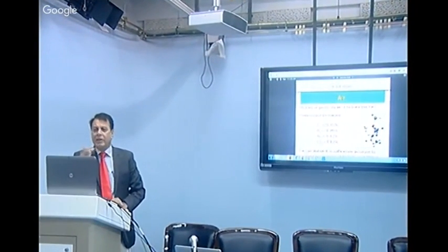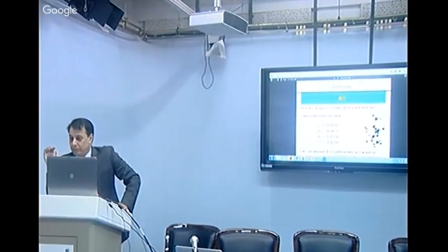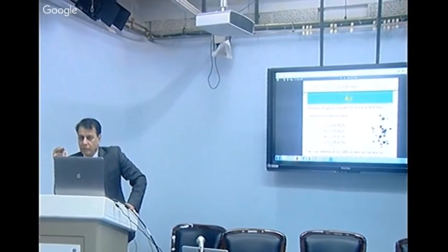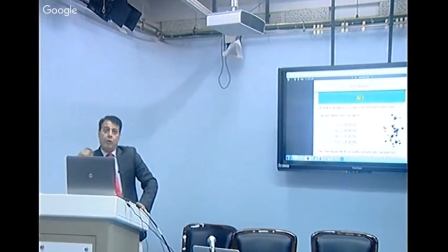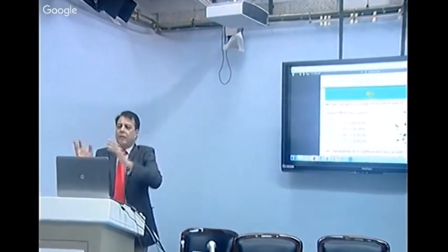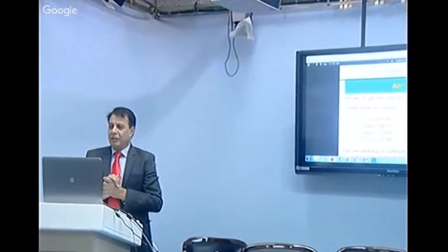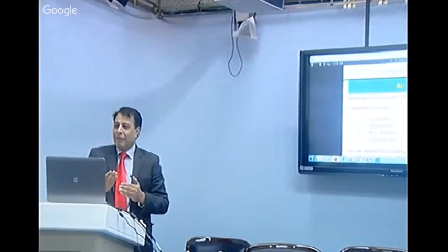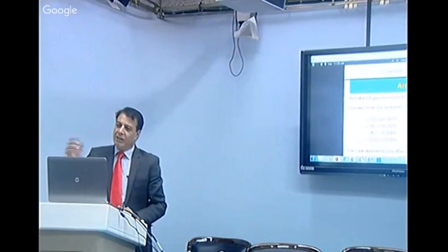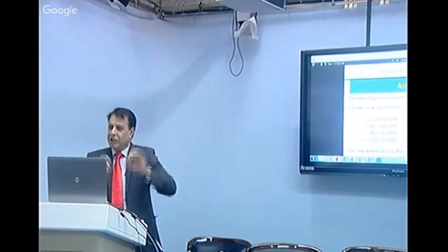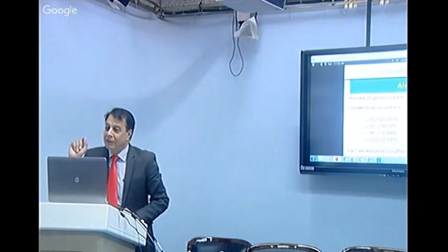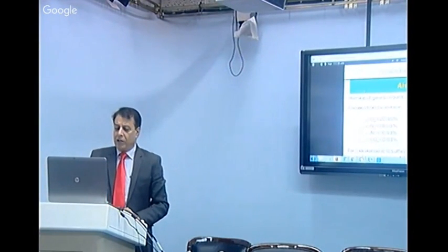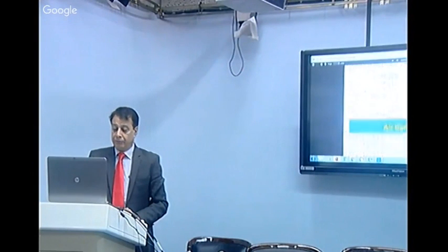Now, whatever we have discussed till now, is it clear to you? Right. Earlier I was using a carburetor, and a carburetor cannot compensate for all these variations. You understand? If the temperature is high, the carburetor jet is fixed, so it will give the same quantity of fuel. Another important thing I am going to tell you.